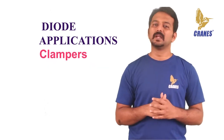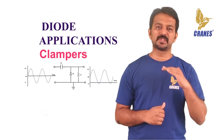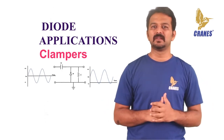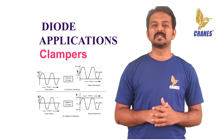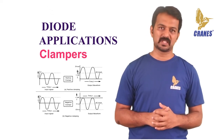So the next one is diodes in clamping circuits. A clamping circuit is used to shift or alter either the positive or the negative peak of an input signal to a desired level. This circuit is also called a level shifter or a DC restorer. These clamping circuits can be positive or negative depending on the diode configurations.